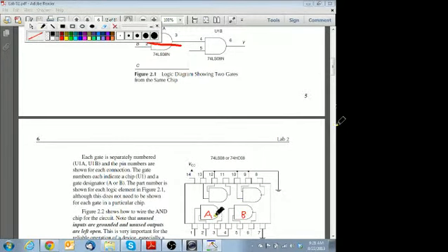Now the data sheet may not tell you which one's A and B, but your documentation in your schematic will define what A and B is. Really, it's defined by whatever CAD tool you use to draw it. But normally they should go in order, from pin 1 through 4, this way. So it really should go A, B, probably C, and D. That's the more standard way of doing it. But if it's ever in doubt, just make sure you follow whatever's on the schematic.